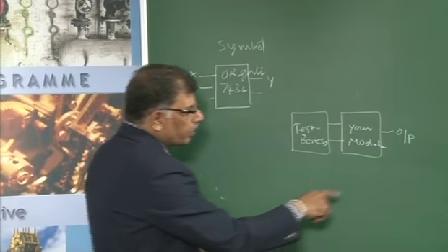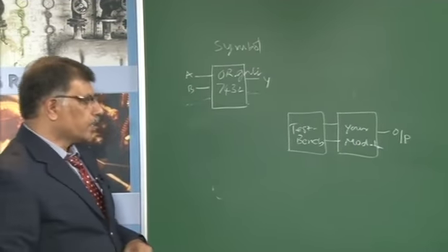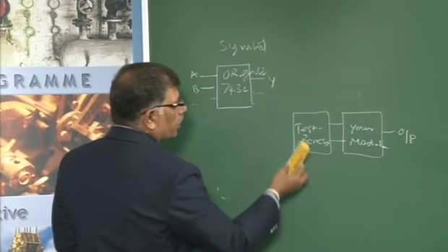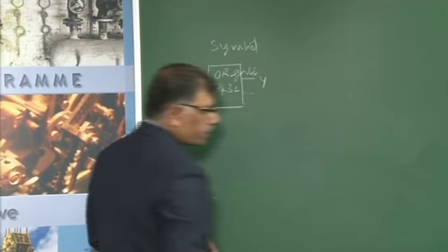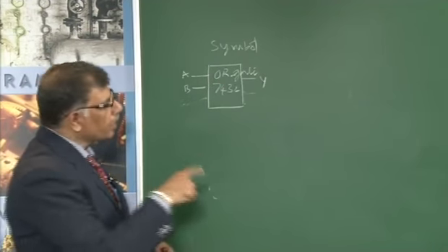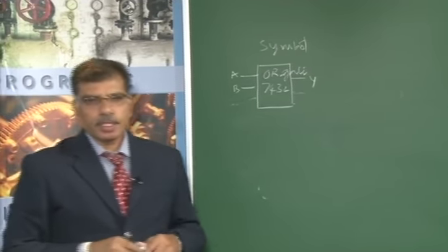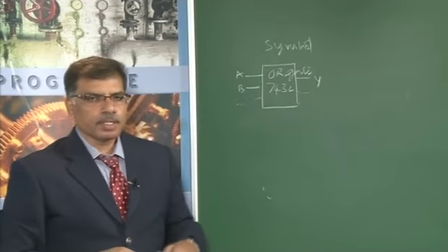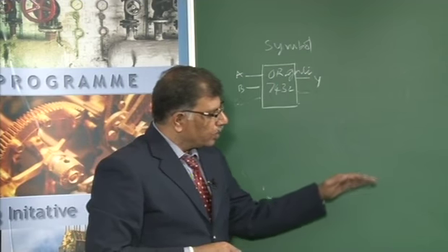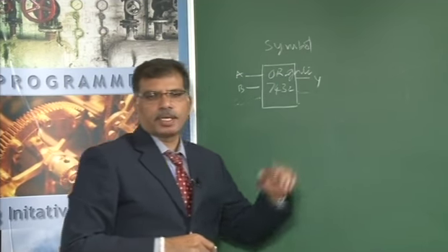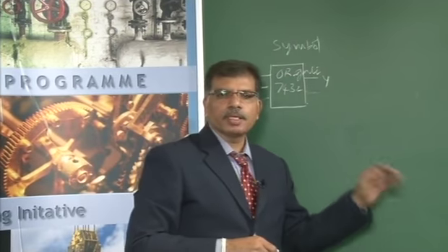The program that I have written in terms of an OR gate is called data flow coding. There is another way of writing it. I will try to write a gate level coding, or structural coding, for an OR gate itself in Verilog, because according to the prescribed book in the syllabus, he majorly uses Verilog rather than VHDL programs. So I will write the description for an OR gate at all the description levels, and I will tell you how to write a test bench for simulating those models.